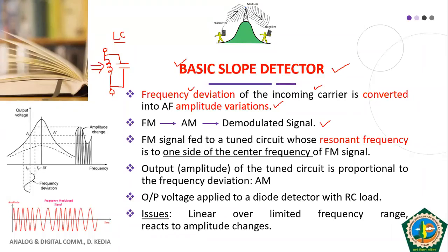Your signal enters into the filter, and depending on the resonant frequency of this LC filter, a given frequency is passed through. If the frequency of the incoming signal lies in the pass band of this filter, then that frequency is passed as such, and if the frequency is different, then that signal is attenuated.